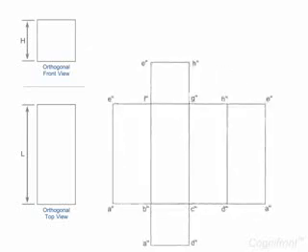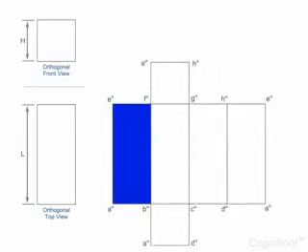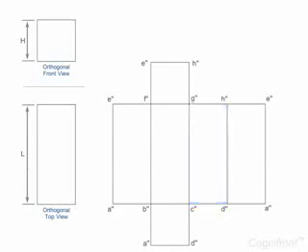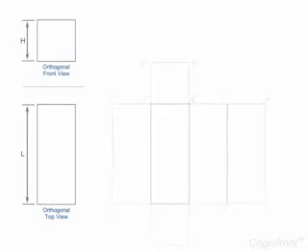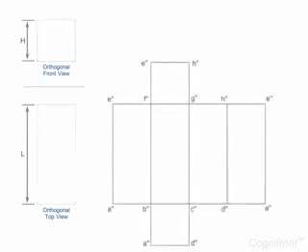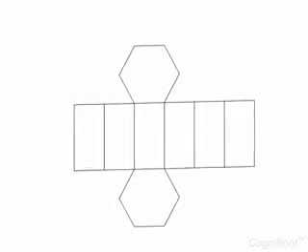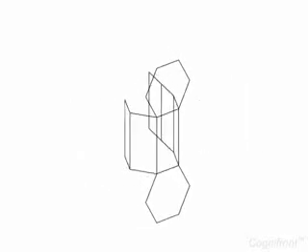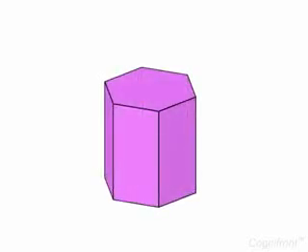Then its developed surface view will appear as 4 equal sized rectangles, each rectangle being the size of the longitudinal side of the box. The flaps of the boxes stand out as separate squares. Here, the surface development of the carton was done with the help of orthogonal views of the object. In general, the final fabricated product is made up of various geometrical shapes.